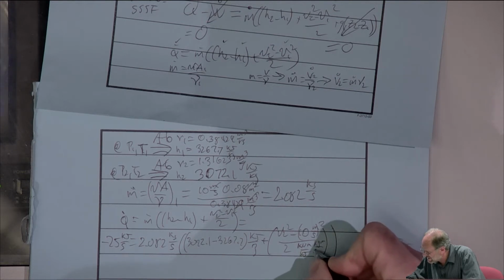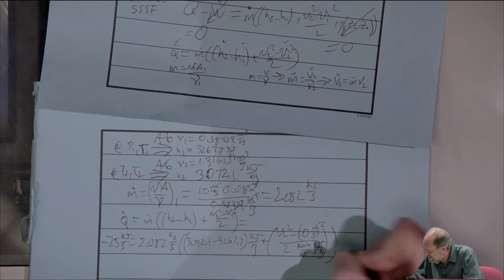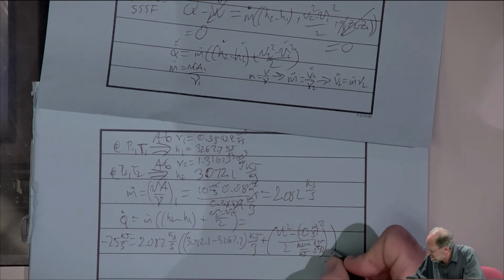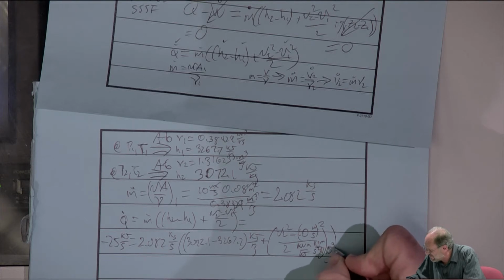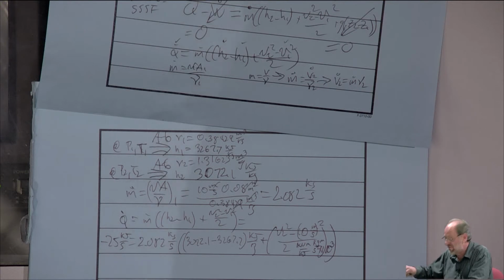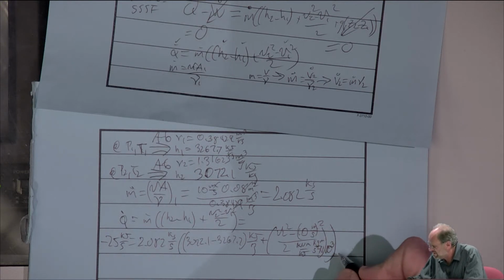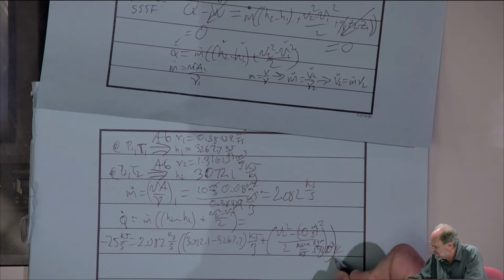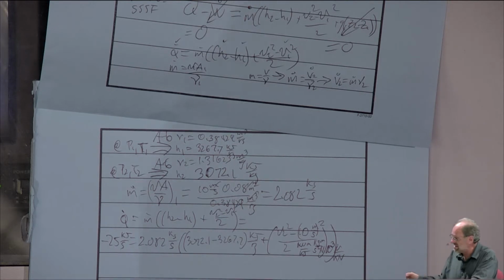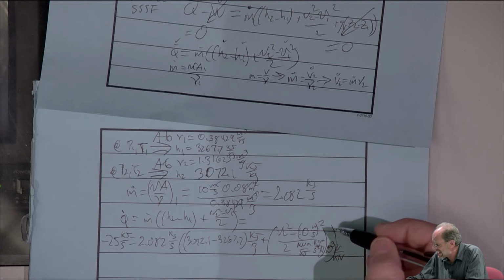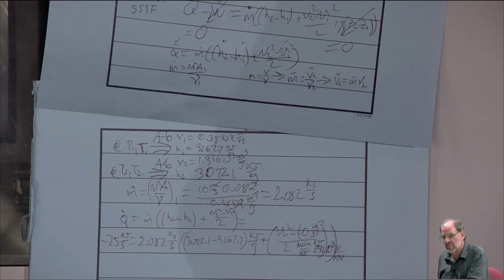Kilogram meter per second squared per Newton. Oh, and then we also know that there's 1,000 newtons in a kilonewton. So we need a 10 to the third in the denominator. I really need to move this right-hand bracket out further and leave myself enough room. So we also have a 10 to the third in the denominator, which again is going to be newtons per kilonewton. And now you can see that everything works out properly, right? Everything cancels out except kilojoules per kilogram.